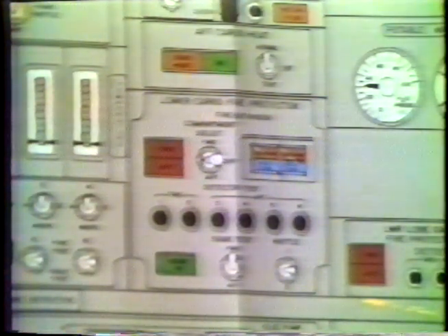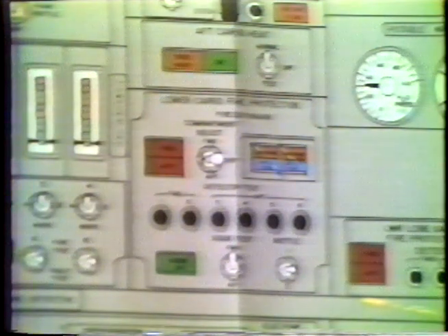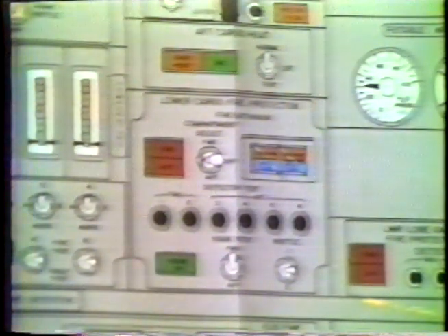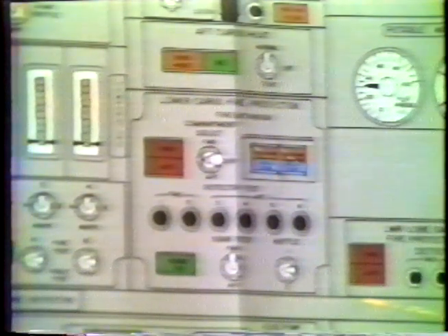It's a little photoelectric light on a target, and if the obscuration between the light and the target gets to the point where the light cannot reach the target, then the fire detection activates. Since it is not temperature sensitive, we've had some problems in this area by maybe an insect or a baggage tag causing a fire warning light to come on. There is very little possibility of visually checking the cargo compartments in case of a real fire.